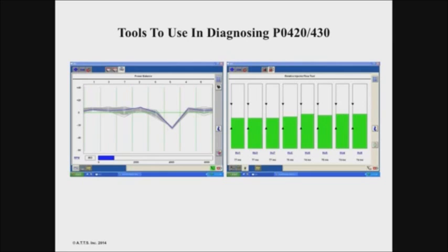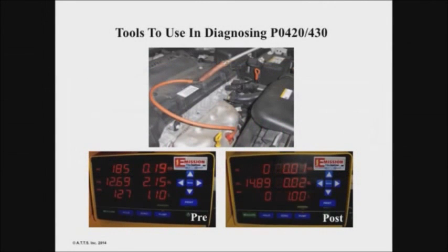Here we can use a gas analyzer. You know, the thing that no one likes to use anymore? Gas analyzers are important. Just one thing in this whole gas analyzer right away: Lambda is something that you should look at instantly. And how long does it take you if you throw it in the tailpipe? You're there. You can see if you got a problem. Okay. So here on a Hyundai, there's a little piece I made up. Okay, that little rubber hose, I got my gas analyzer.